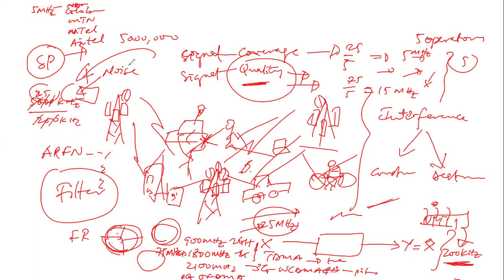Now, there's a big difference between noise and interference. We deal with noise on the circuitry side. We may not have control over it: white noise, shot noise, and all of those. The distortion of the signal relative to that, we cope with. That's why we have filter designs on the circuitry side. We use either active or passive circuit elements to design filters to resolve some of those problems. At some point, if the signal is being attenuated, we find a way to amplify it, so we use active devices like amplifiers to amplify the signal in the signal processing dimension.